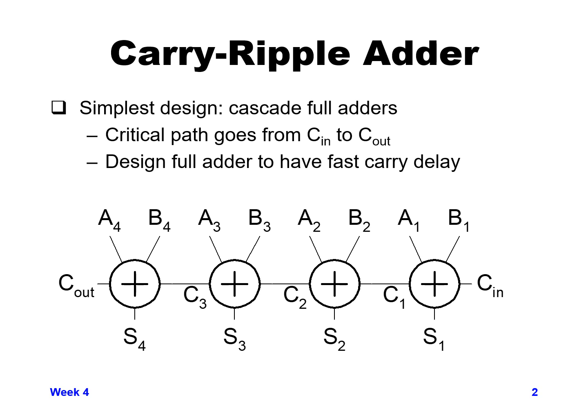If you take each individual stage and cascade the C out from that stage to the C in of the next stage, this allows us to make a functional design. It works, but this will be the slowest carry path. You have to go carry in through carry out of each bit in order to get all the way through.